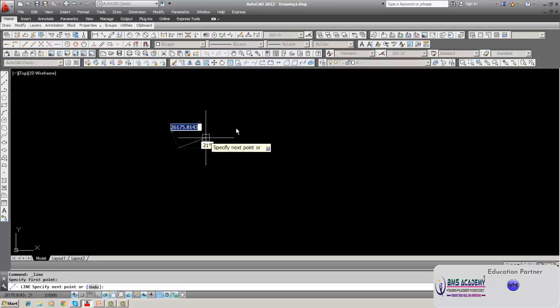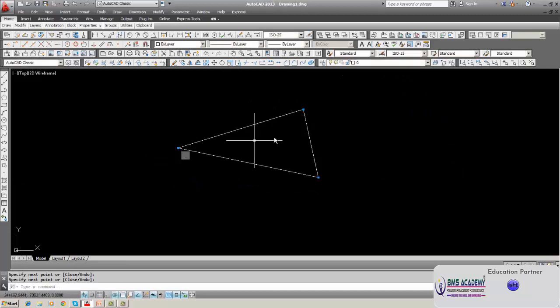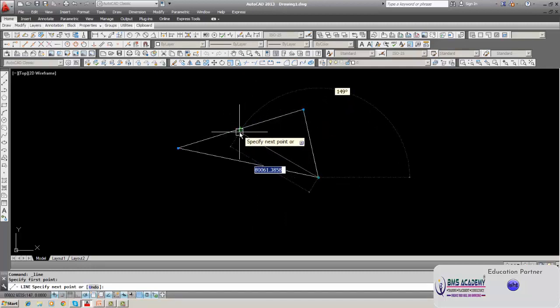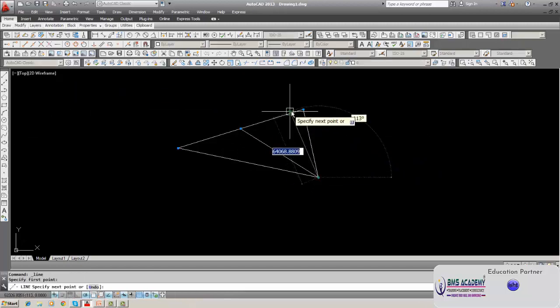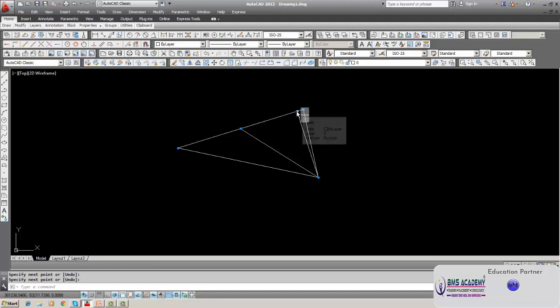Suppose I draw a triangle. See, you have applied a constraint here, a constraint here, and a constraint here. Because we have selected auto constraint, it is applied. Okay. And similarly, I will draw a perpendicular from this point, or say the midpoint, to join. Here also it is applied. The constraint is applied automatically. And suppose I draw a perpendicular here. So here also the perpendicular is applied. The line is perpendicular, and also another is coincident.